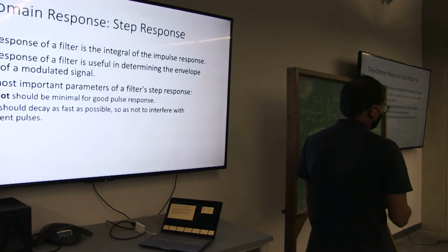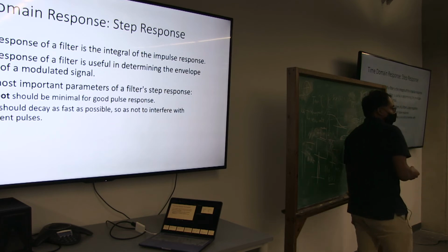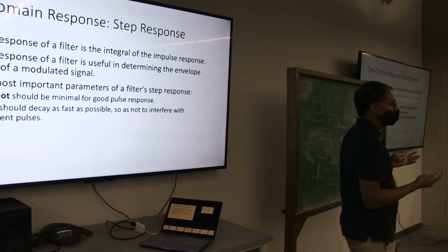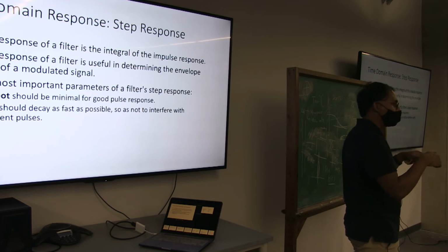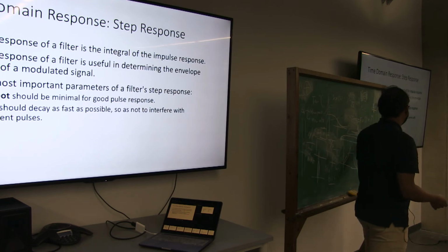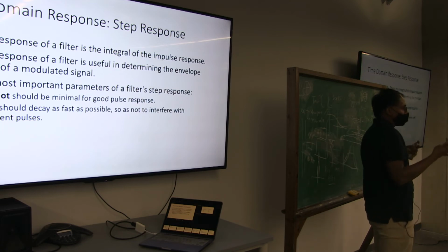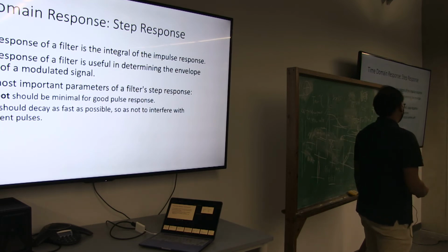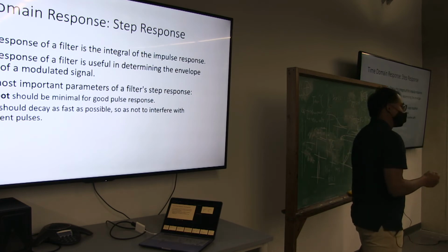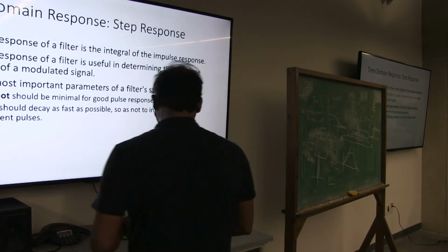So the rise time and the settling time is another key important specification. In the real world, when we are designing in industry, they'll tell us, okay, this is the rise time of the black box I want, and it should settle within 1 microsecond, or it should settle within 10 microseconds, it should rise within 1 microsecond. These are the kind of specifications we'll get as designers, and we should be able to translate these back into filter specifications and start designing. So step response will give us that tool to do that.